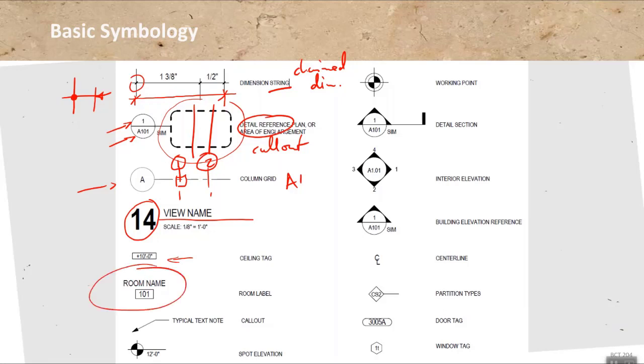Room labels are really common. You'll find them in all kinds of spaces. It doesn't necessarily need to call out a room. This could be calling out a portion of a room, especially if it's an open space that's subdivided into things, cafe, atrium, all of those kinds of things. And so that's fairly typical on floor plans, where you then obviously have the actual room name. Then every space is numbered, so that numbering below represents that, and then sometimes you also have square footage underneath.